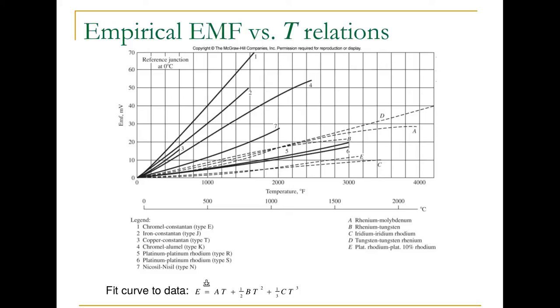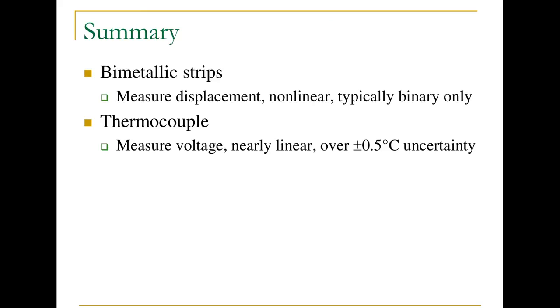Instead of linear interpolation, one could use a curve fit to get a better approximation for the intermediate values, and a third order curve fit is often adequate. And this is given in the textbook. Equation 8.12 yields the polynomial for curve fitting the data from a thermocouple table.